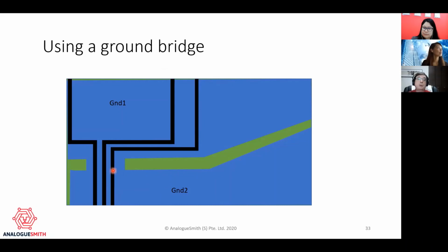Now, we obviously are putting signals close to each other and they can talk to each other. So it's not a be-all ground solve problem from that point of view. You will have to check that these aren't coupling to each other. If they are, you may have to have another ground bridge at some point. There can be all sorts of issues involved, but this is the way that you move signals between ground planes on a PCB, okay?